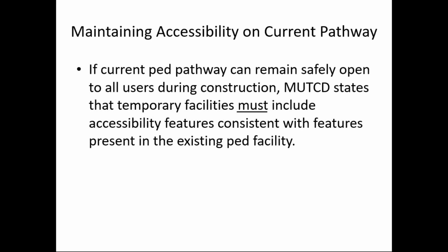We maintain accessibility on the current pathway. The MUTCD says that these temporary facilities have to include the accessibility features consistent with those on the existing facility. So if it's a concrete sidewalk, the temporary facility doesn't necessarily have to be concrete, but it needs to be firm, stable, and slip resistant, and have sufficient width and appropriate cross slope.